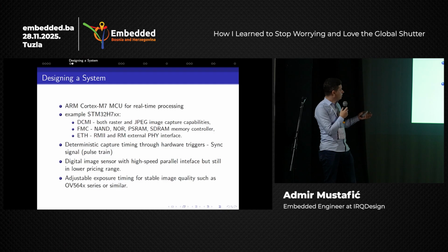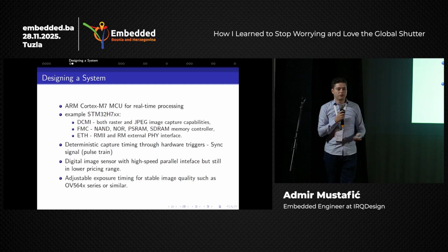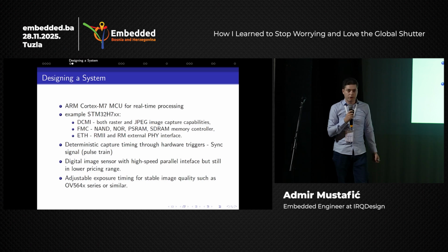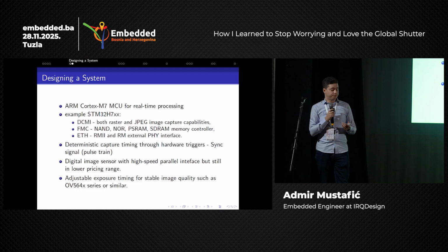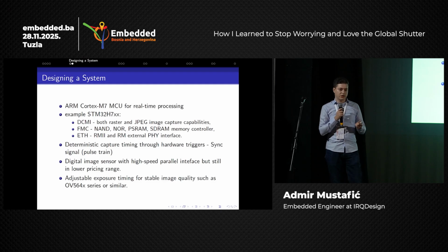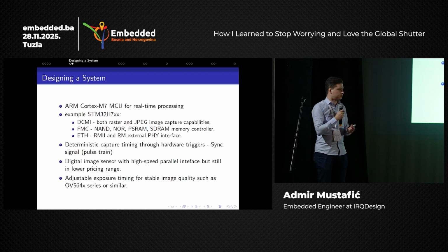For example, a camera used was from the OV564 family. The specifics of this camera is that it has a Frex mode or global reset mode, which mimics global shutter mode. It is still a rolling shutter camera, so the problems that we have with the classical cameras still occur. Each data is read row by row, so we have such a timing offset where we will have the jello effect or the distortion, and the object will not seem static like it's supposed to, like in the global shutter example.